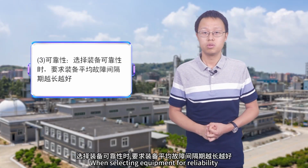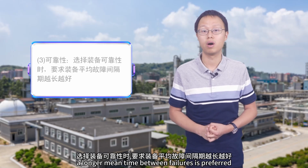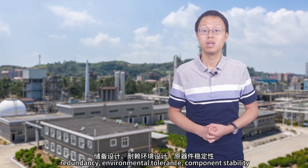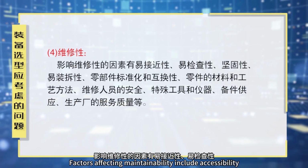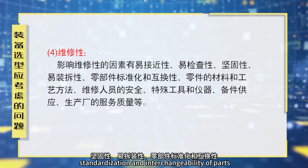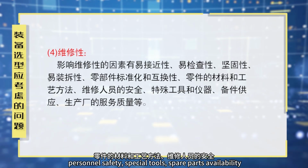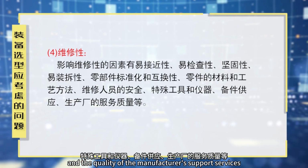Third, reliability. When selecting equipment for reliability, a longer mean time between failures is preferred. This can be analyzed in terms of design safety factors, redundancy, environmental tolerance, component stability, fault protection, and human factors, ergonomics. Fourth, maintainability. Factors affecting maintainability include accessibility, inspectability, durability, ease of disassembly, standardization, and interchangeability of parts. Material quality and manufacturing processes, personnel safety, special tools, spare parts availability, and the quality of the manufacturer's support services.